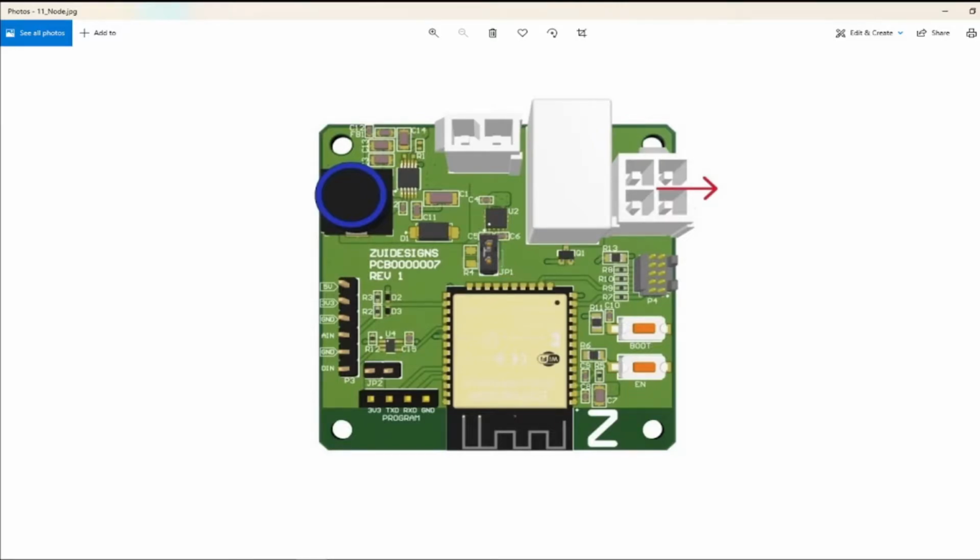The lower half of the board provides various connections for interfacing the ESP32 module with external devices. This allows for task versatility between each node in the mesh network. The 6-pin power header on the left edge of the board provides 5-volt and 3.3-volt output pins for powering devices at up to 100 milliamps for each pin. A 0 to 5-volt analog input pin and a 0 to 5-volt digital input pin allow the node to respond to events or feedback driven by connected sensors.